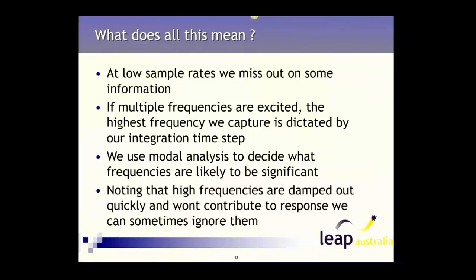Okay, so at low sample rates we miss out on some information, but sometimes we deliberately do this because at very, very high frequencies, those high frequencies are damped out quite quickly. So if you exclude those frequencies by using a high time step, that's not going to make any difference to your results, because those frequencies will have died out quite quickly.